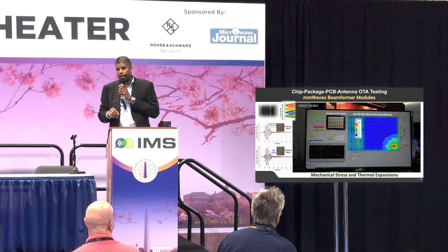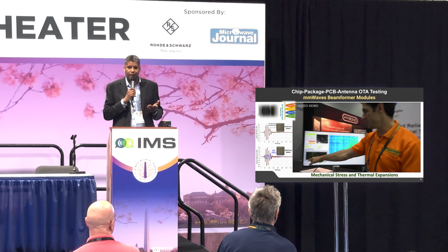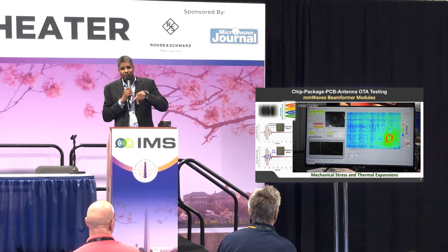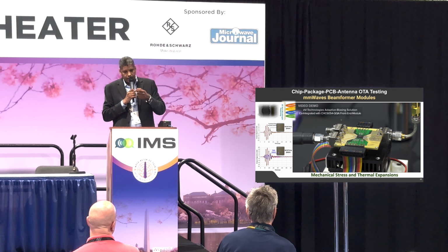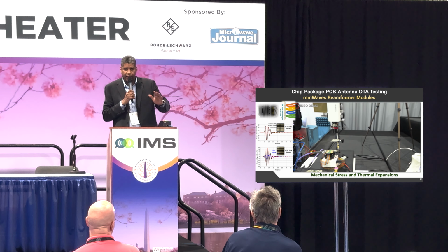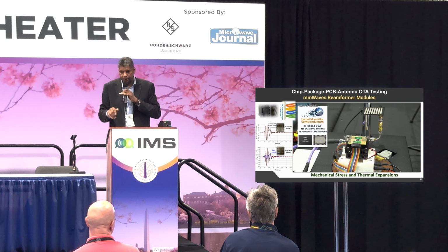And what is interesting is that this can be used to calibrate the phased array in terms of power. Why this is important is that even if the phased array is functional, the peripheral antennas and the inner antennas will never deliver the same power because of adjacent coupling. The inner antennas have 4 neighbors, so you have proximity effects. The peripheral antennas will see different boundary conditions. They have only one single neighbor. So by looking at the dissipation, you could correlate that power level, and it can be a very easy way to calibrate the power levels, at least the DC.